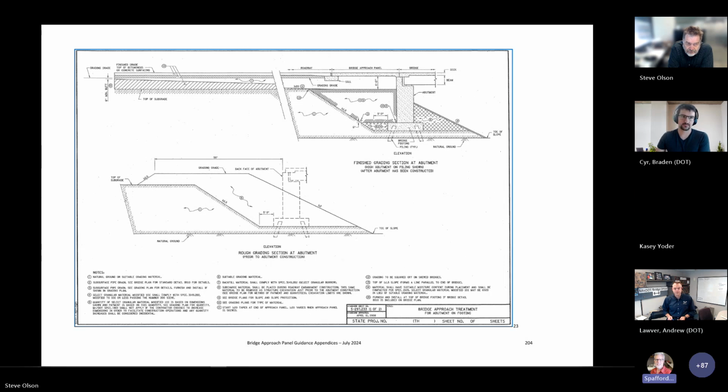Exactly. And the age of the concrete. If they use an epoxy, it doesn't like moisture, so it's not going to hold. They're going to float out. Getting a drainage tile in there is going to be really, really beneficial, and making sure that it gets three-quarters of an inch to an inch below the roadway surface, so it doesn't get the tire slap.